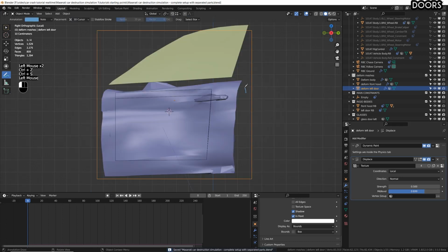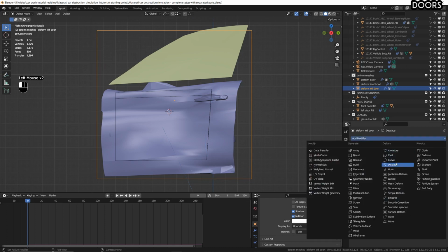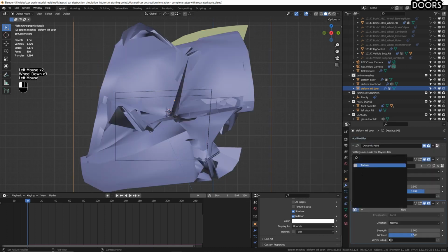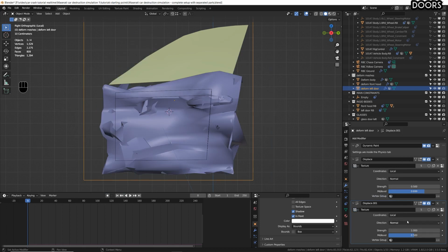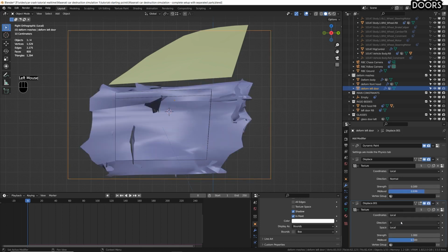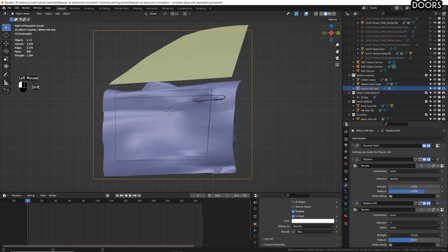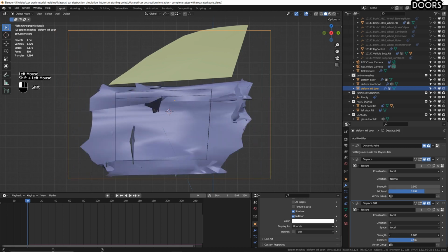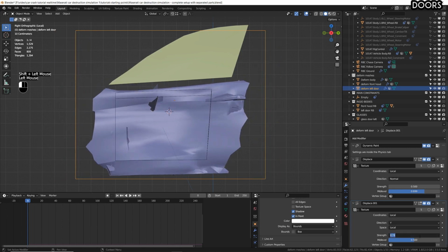All right. Now I want to give a secondary displacement for pushing this geometry in this direction, more or less, like this. Because this part of the door, of course, is gonna hit everything is gonna meet on the road during an accident. So let's give another displacement, add modifier, displace, texture, is gonna be this one. So for the direction, I'm gonna change this to the Y direction, which is as before this direction here. If you try to tweak it, you can see what this is doing. So something like 0.5, don't exaggerate.